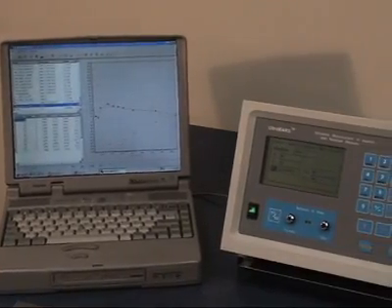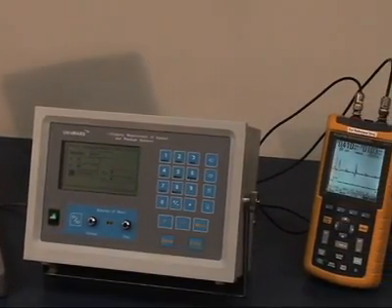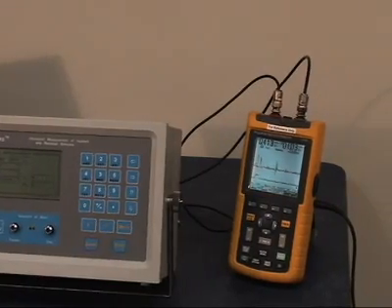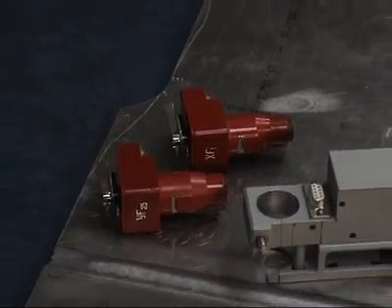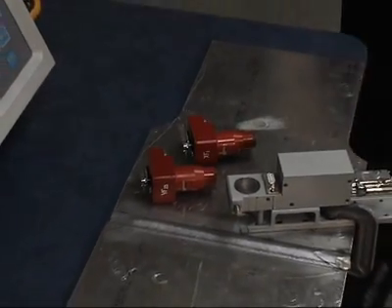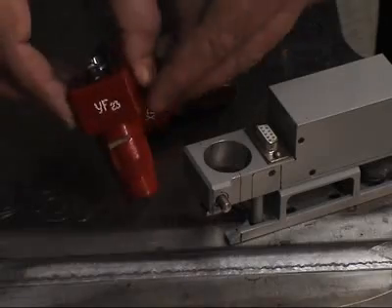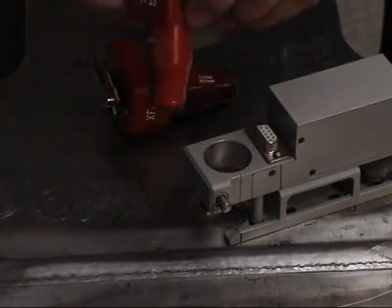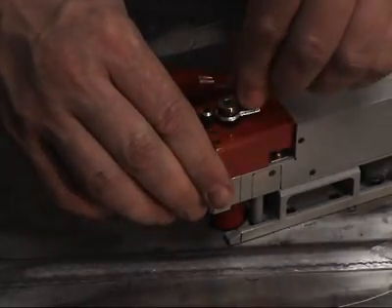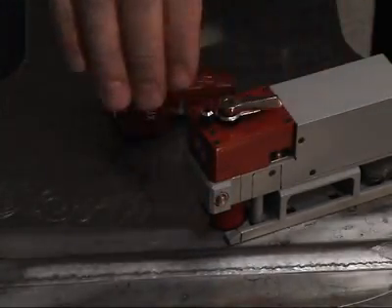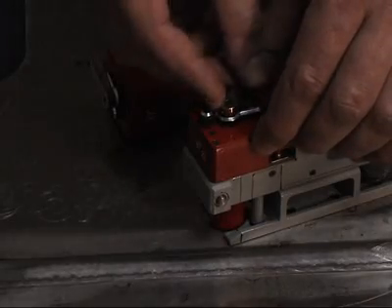Ultrasonic peening treatment efficiency can be evaluated based on ultrasonic measurements of residual stresses in welded elements before and after treatment. The residual stress measurement process involves measuring the velocity of 2 shear polarized waves and 1 longitudinal ultrasonic wave at the specific point of interest. 2 different gauges are used for this purpose. The first gauge measures the velocity of the shear polarized wave parallel to the weld. The same gauge is then used to measure the velocity of the shear polarized wave perpendicular to the weld.